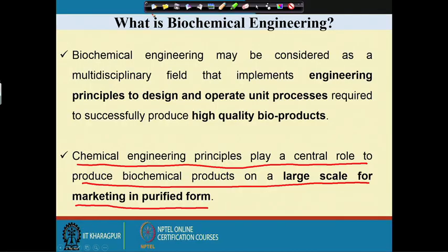So this is how, suppose we want to produce 4 tons of citric acid by using Aspergillus niger, we can find out through this analysis what will be the size of the reactor for getting the 4 tons of bioproducts, both in the batch process as well as the continuous process. So this is the information that we want to give you through this project, and at the end of this project you will be developing the expertise for doing this particular analysis.